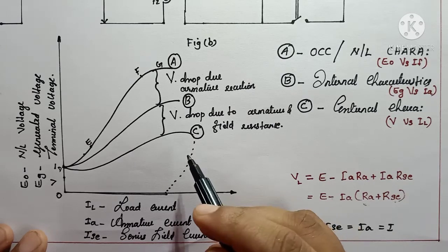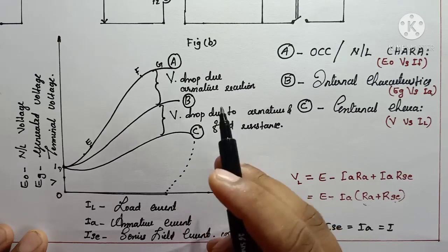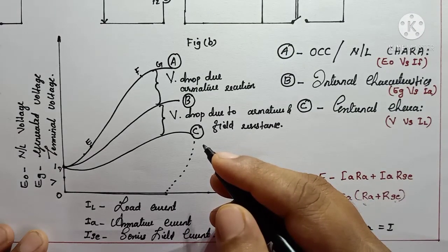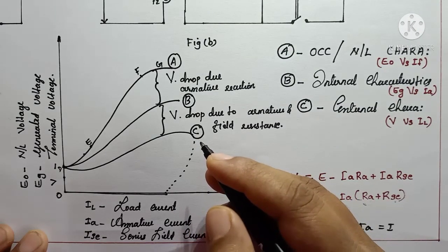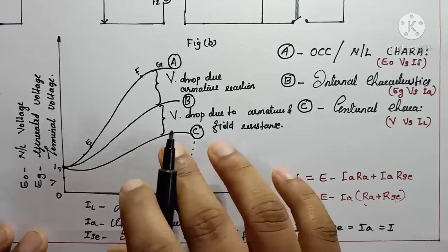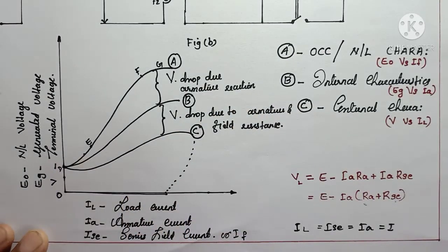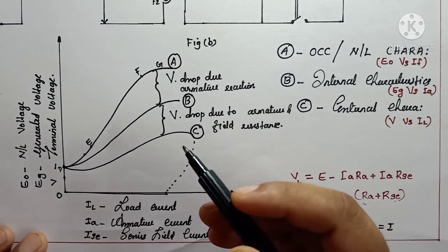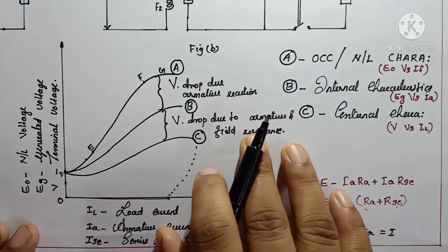They are also used for supplying field excitation currents in DC locomotives for regenerative braking purposes, and as boosters in feeders for various types of distribution systems like railway service, in order to compensate the voltage drop in the feeder. And in series arc lighting we can use these generators. These are the major areas of application of this type of generator. Okay, thank you.